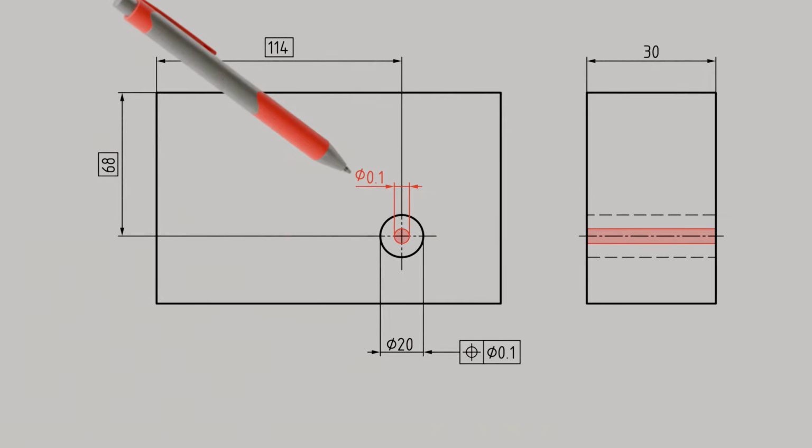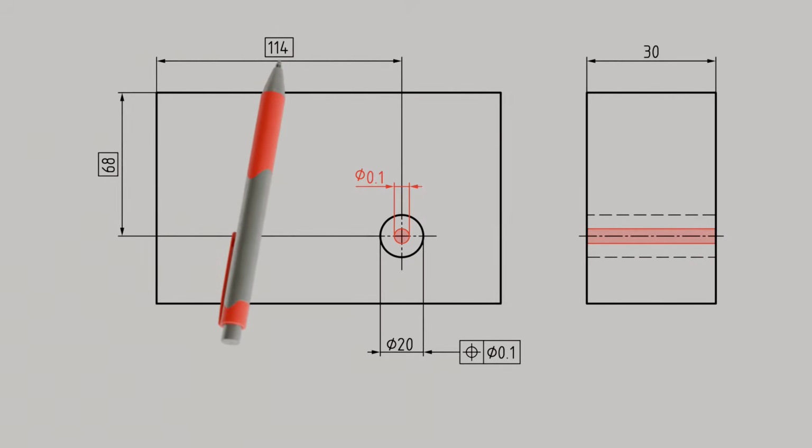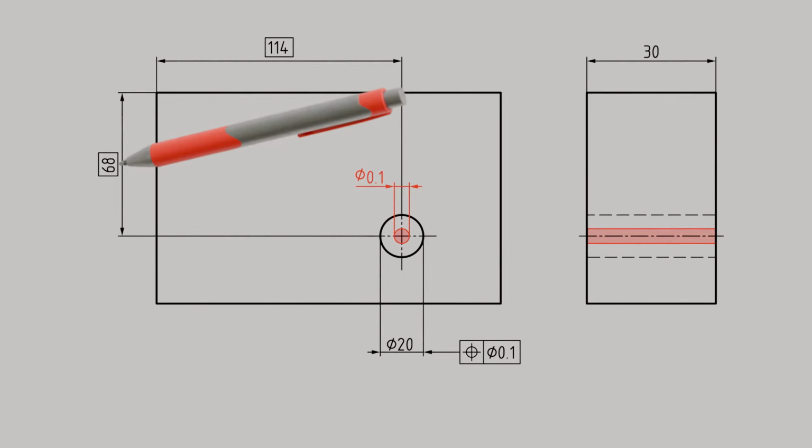mm, where the axis of the tolerance cylinder must be located at the theoretically exact position defined by the dimensions given in the rectangular boxes. Note that no dimensional tolerances apply to this theoretically exact position. We have now avoided the first mentioned problem of the rectangular or cuboid-shaped tolerance zone and replaced it with a cylindrical tolerance zone. Now the second problem of correctly aligning the part must be solved in order to determine the theoretically exact position of the tolerance zone.